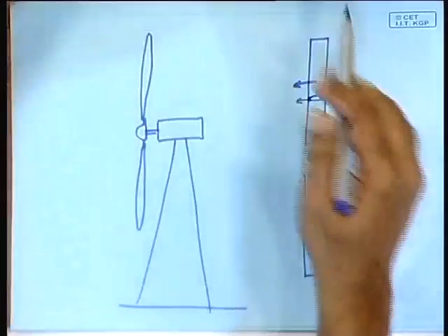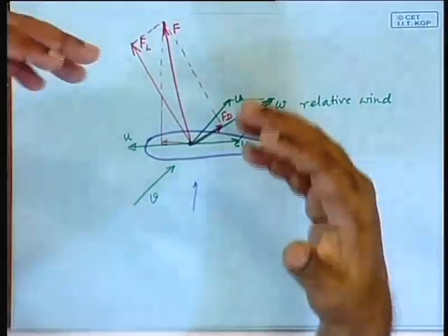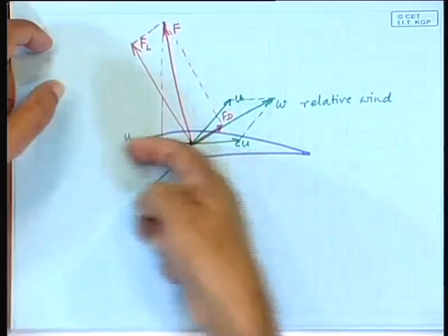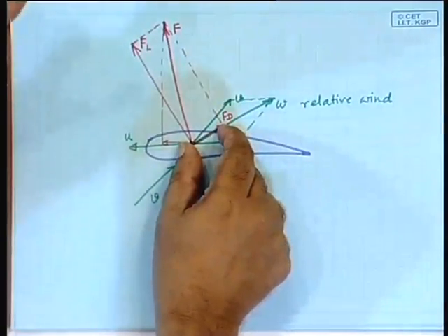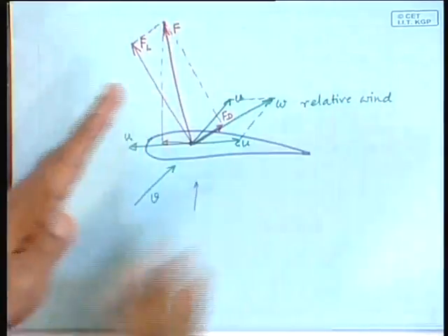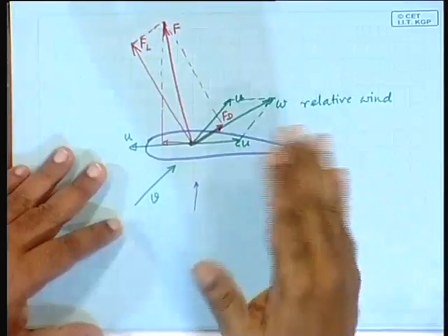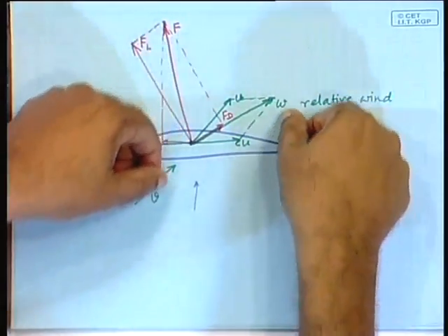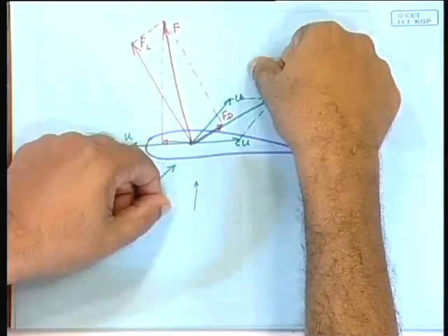And normally, okay, it will not be difficult for you to understand at this stage. See, you would like to minimize the drag and maximize the lift, because drag is acting in the opposite direction to the lift. The more the lift, the more this force. So, you want to reduce the drag, and what was drag proportional to? How much area does the wind see, accordingly it tries to push back. So, you would like to make sure that it sees the least area, and when does it see the least area? When this airfoil is oriented in the direction of the relative wind.